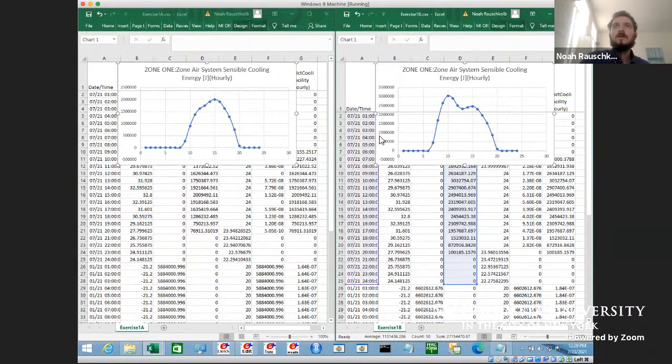So you can see in our 1B, when I add the east facing window, we have this morning peak because there's a lot of solar radiation blasting in first thing in the morning. Around 10 a.m. it peaks, which is incidentally the exact time that I have to turn on my air conditioner every morning in the living room. And then as the sun continues to rise and we no longer have the radiation directly on the east face, our load actually drops a little bit.